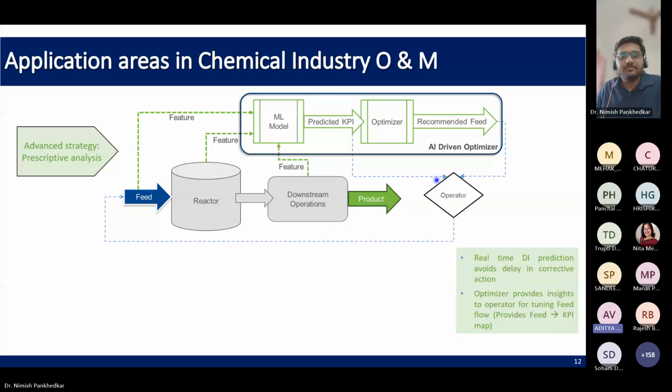So there will be an equation that is developed for interaction between all parameters, and then that will be optimized over several runs. Correct. And the final equation that gives you the optimized conditions will be fed to this APC model that you are suggesting instead of the operator. Right. So basically, what you get is the set of best operating parameters as your output from the optimizer. So whatever the operator does manually, you can automate that with the help of the optimizer. Because every time in real time, if you are sitting on a DCS panel, you will not open Aspen, and we cannot try to do a simulation.